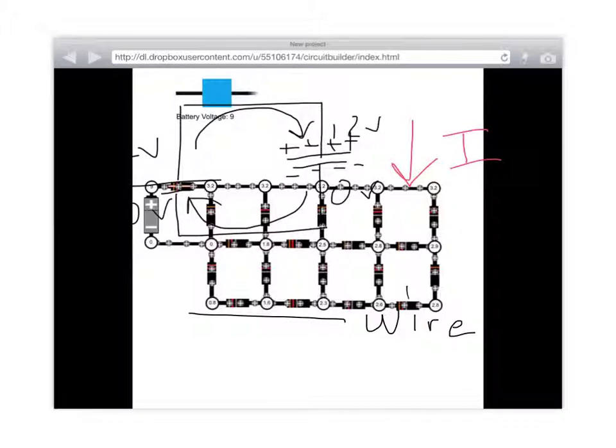A fully charged capacitor looks like an open circuit. Why? Well, it's an open circuit because no more charge is flowing, right? All right, ponder this as you solve the capacitor network problems. Go.